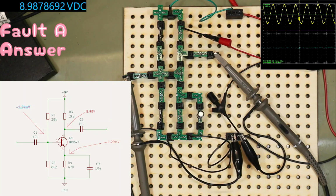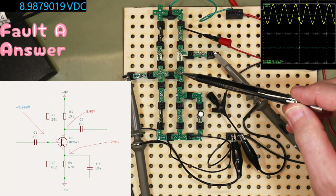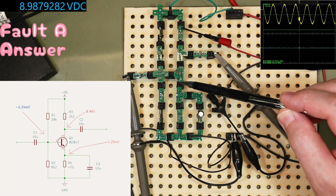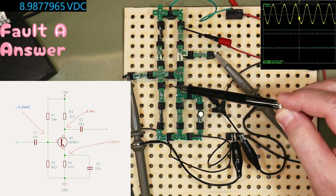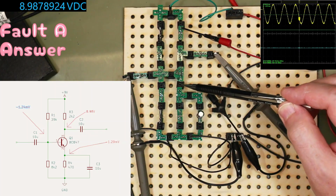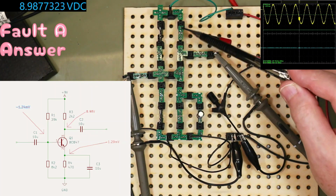Right, this is a simple fault. There is a simple fault because we should be expecting 0.6 of a volt, or 0.7 of a volt, base to emitter. And what are we getting down there? Virtually nothing. So that point there and that point there are basically at ground, which means for that to be at ground, no current flowing. For this side to be high, no current flowing.